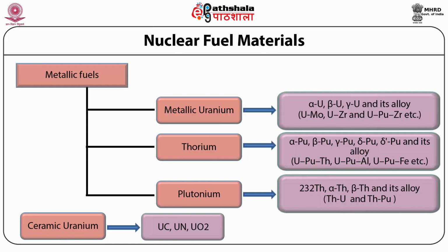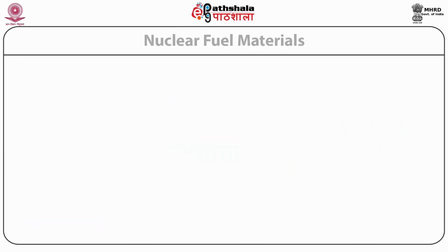After a few years, the changes in fuel element design opened a gap between the nuclear fuels and cladding materials that gives a plenum volume for gathering fission gases and presented significant improvement, 1% versus 20% burn-up over the earlier designs.